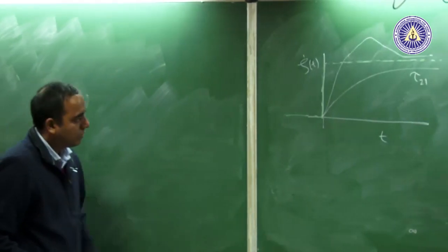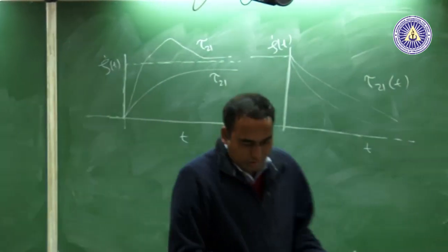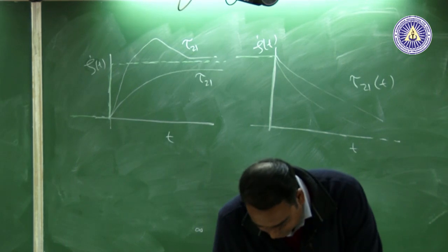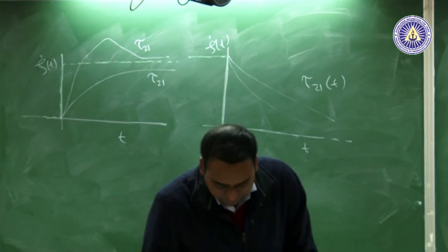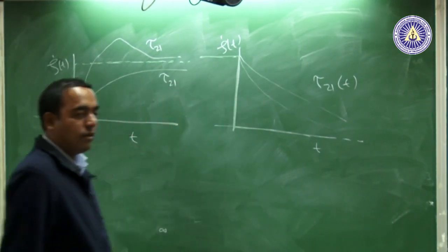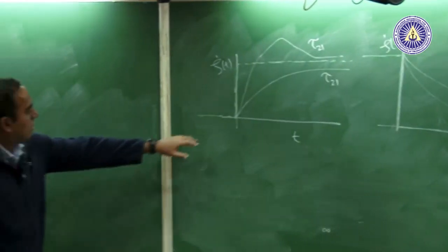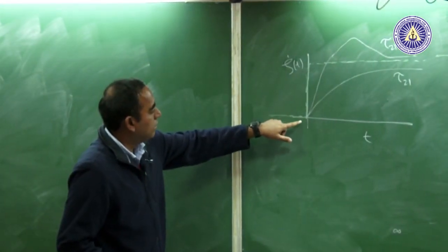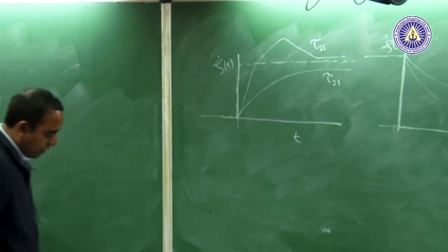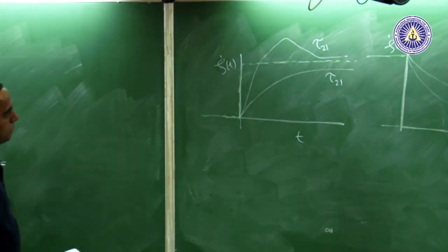The way people answered it is, for these sorts of experiments and the typical curves that you obtain, the GNF or the Newtonian fluid instantly hits a new shear rate, whereas in an actual experiment it does not.